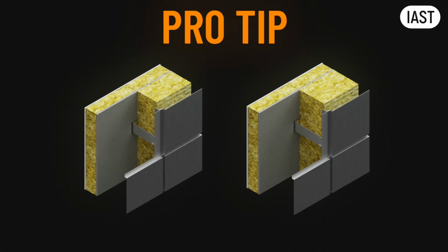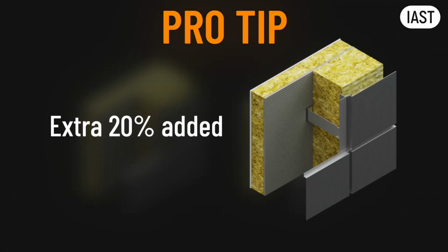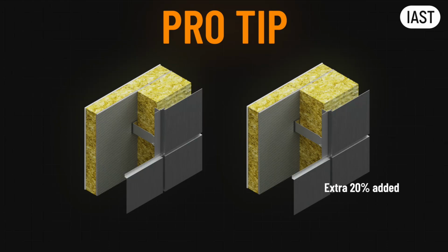My personal advice is overshoot. Add 20% more insulation than the calculation says you need. That buffer will be eaten away later by the thermal bridges you have not found yet, the brackets you did not know were there, or the slab edges you missed. Trust me on this one.